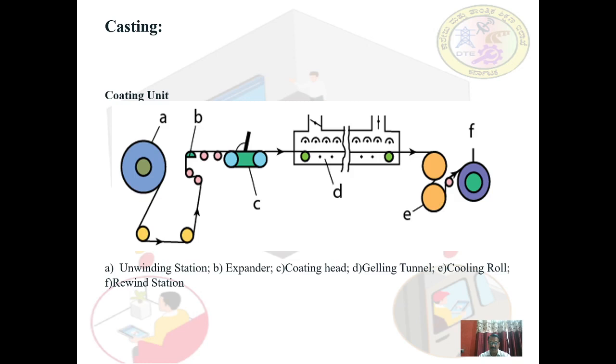Thereafter, a doctor blade is employed to spread the paste to the required thickness. A revolving roller supports the sheet, due to which an extremely defined contact area is maintained. The rolls distribute the escaping paste and form a film. The rotation speed of the rolls can be adjusted.